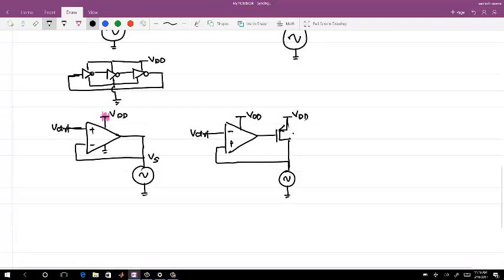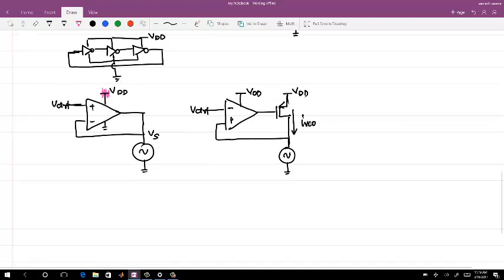Now all the current for the VCO is coming from the pass transistor itself. This relaxes the current requirement on the amplifier. But this has two kinds of paths for the supply noise. One path is coming from the supply, meaning we cannot say that the amplifier is a clean supply. One noise is coming from the amplifier, and the other noise is directly coming from the pass transistor.